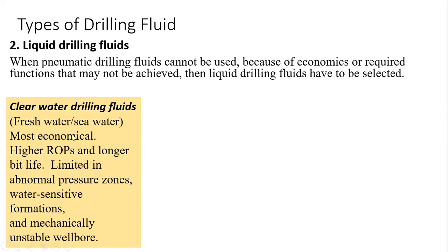So I was saying that with clear water, you can use seawater, and it's in abundance, so it makes it more economical. Using this type of drilling fluid also helps us achieve a higher rate of penetration and a longer bit life. It helps to preserve the drill bit more.